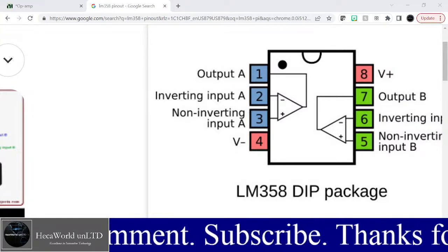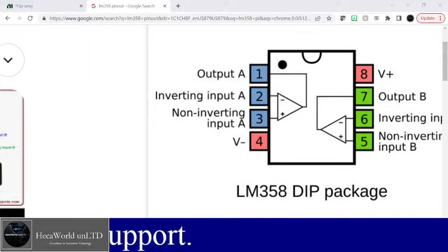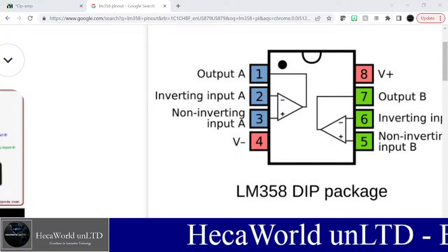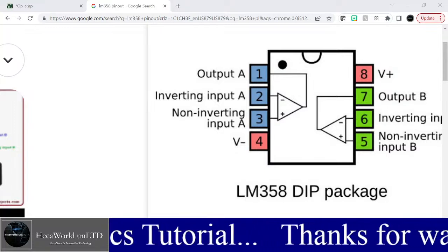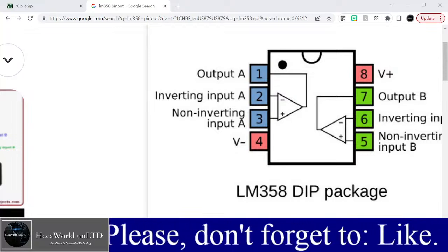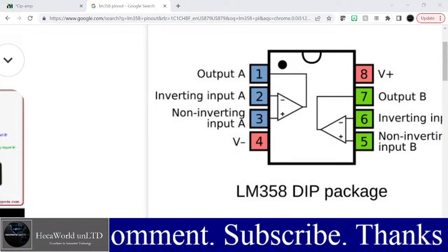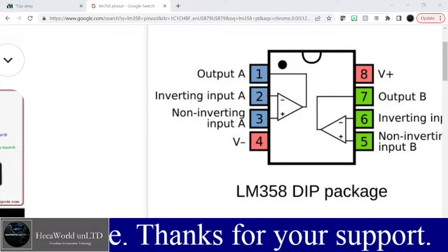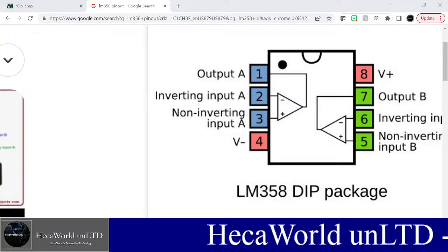And in this schematic, the signal going to this pin 5 came from the other side, pin 1 of the other half of the op amp. So we knew that the signal is already amplified, is outputted on pin 1, and should go to the speaker. But because this design was not made for speaker purposes, it was sent into the input of the other half of the amplifier to function together with other components as the Schmitt trigger.